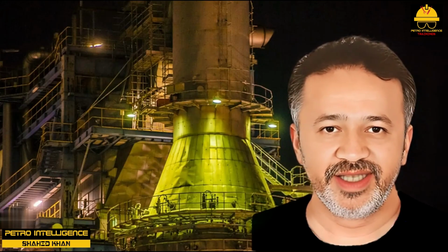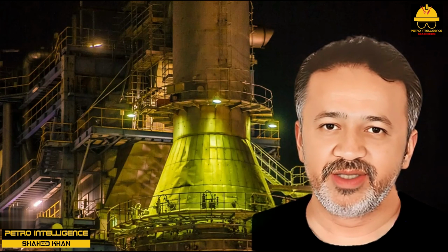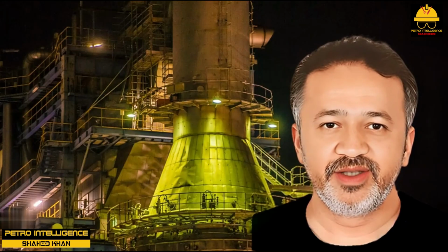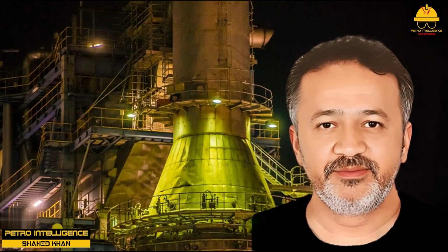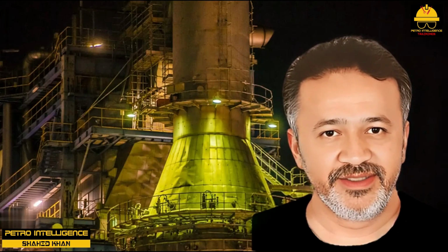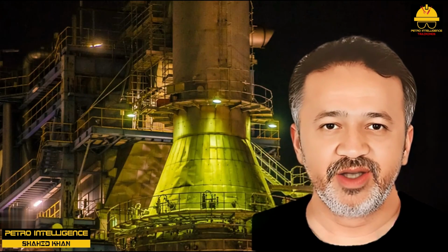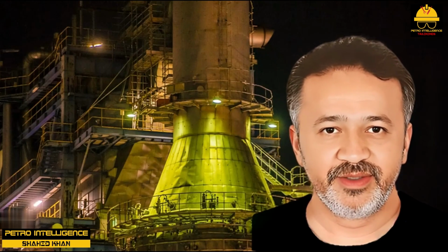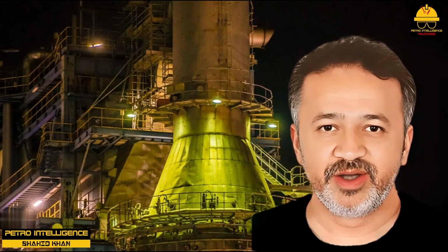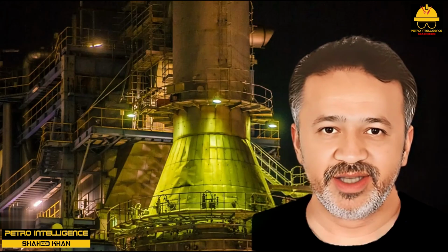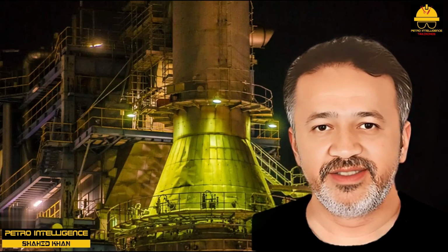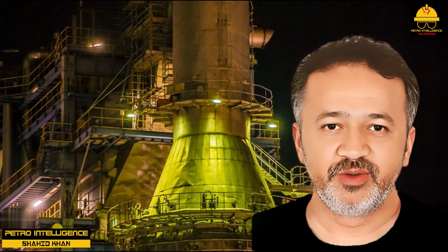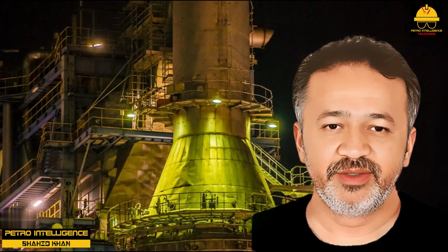We saw this happen recently. When the air supply to the burners was increased, the flame appearance changed from dull orange to a bright bluish yellow. The firebox became noticeably hotter. We assumed, but failed to check, that the stack also became hotter. A hotter stack reduces the density of the flue gas, and that will always increase draft. The airflow was normally restricted to meet an arbitrary, and apparently excessively low, O2 target in the stack. The conclusion, then, is that if opening air registers increased draft, the heater had been operating below the point of absolute combustion. That's all, gentlemen.